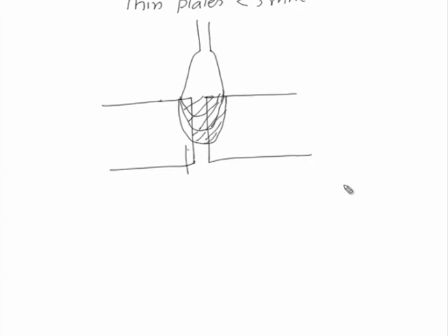this particular portion may be left unwelded. So, if this is the portion which is left unwelded, it will be acting as a source of stress concentration and will not be contributing in any way to the strength of the weld joint.